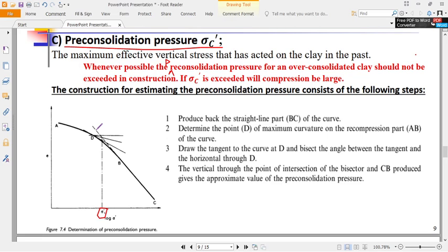So that's one. Now pass through this. The first step is to determine e naught. Remember that e naught is equal to e1 plus change in e. Remember this minus this gives you the change in e for the final. So another thing that we have to determine is e1, at the final void ratio, with the final water content.